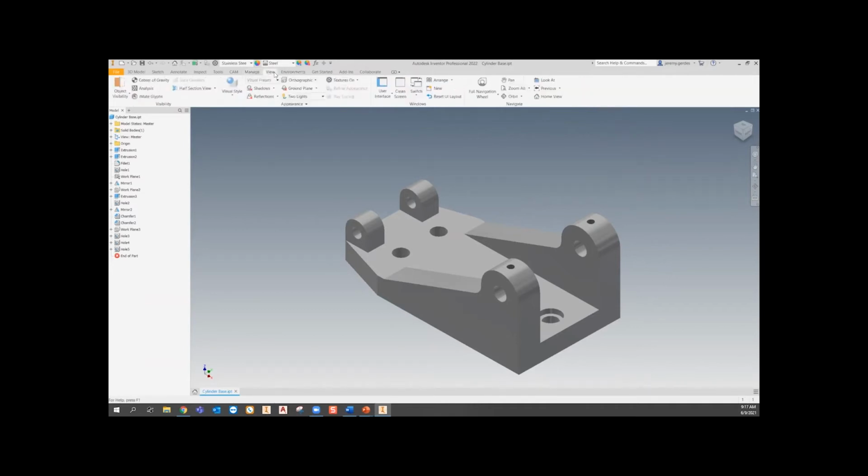So then we'll go to the View tab. The first one is the object visibility. You can turn off the visibility of the planes or the axis, whatever you want. If you don't see or know which plane it is in the tree to turn off the visibility, you can do it this way. You can show the center of gravity. You can turn off the different zebra draft visualizations.